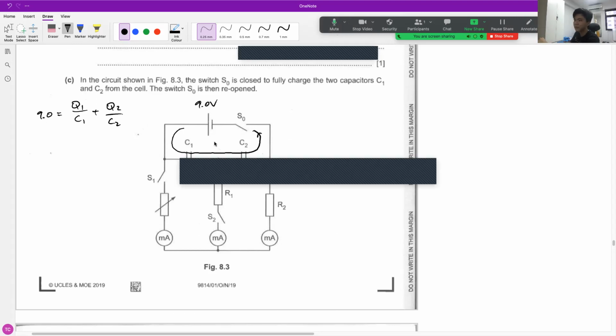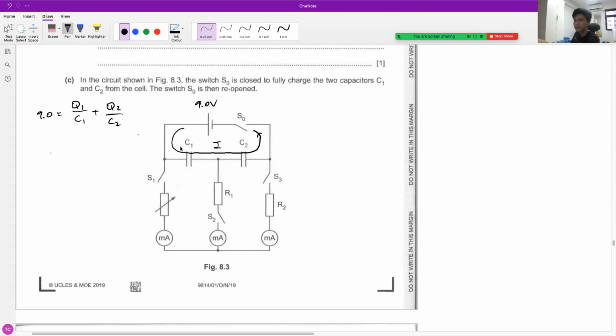So as a result, the charge across Q1 is equal to the charge across Q2. If you have plus Q and minus Q developed like this, because your two plates here are effectively isolated, then by conservation of charge they must be plus Q and minus Q and plus Q like that. So conservation of charge tells you that Q1 equals Q2.